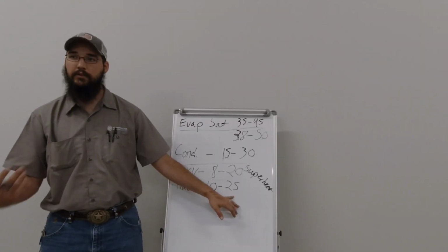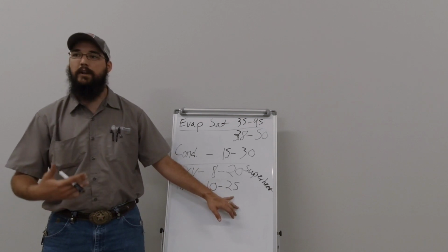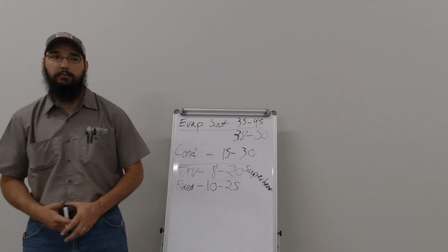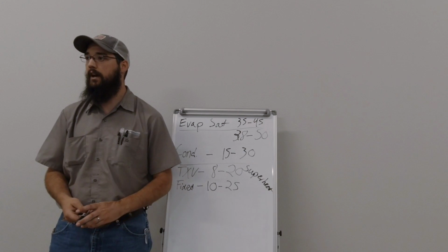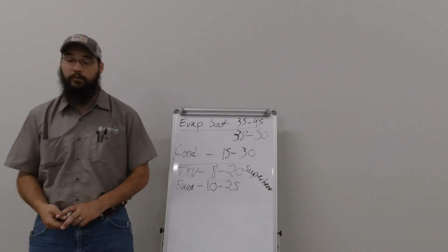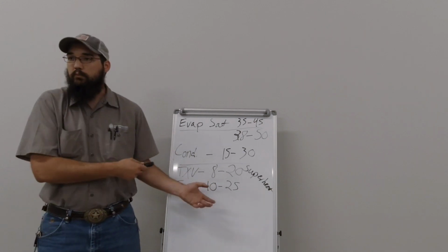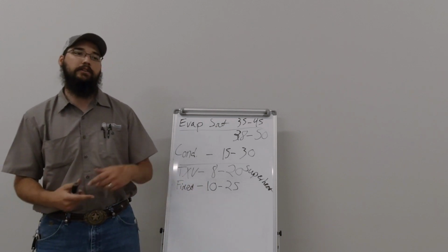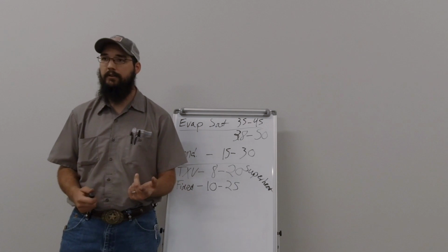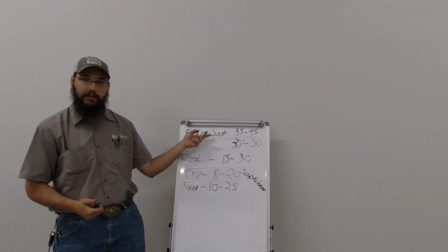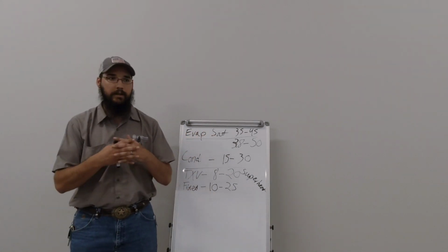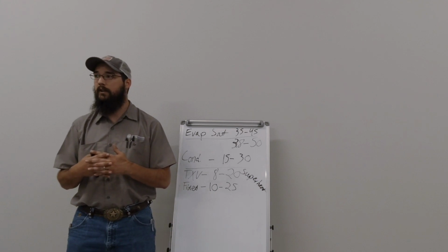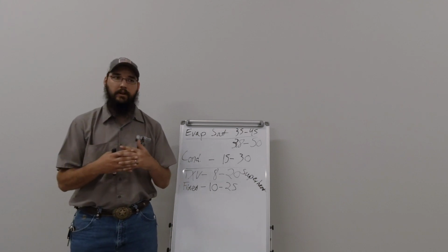So we have to think about those things as we're doing that load and as we're troubleshooting, whether you're charging it or not, whether we're trying to evaluate, is this thing even working like it's supposed to? You've got to look at the return. What the hell is the return doing? That's going to give you an indicator as to what to look for on the evaporator, not only in superheat, but also in saturation. It's all one big piece of the pie. It works together. All four of these are completely dependent upon each other.